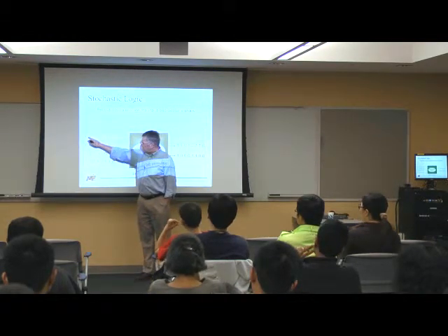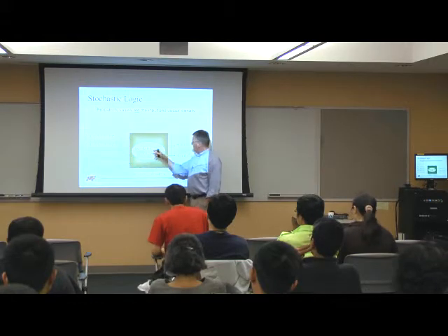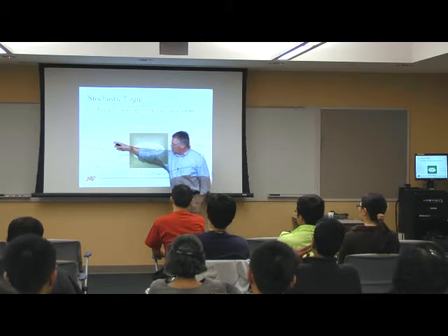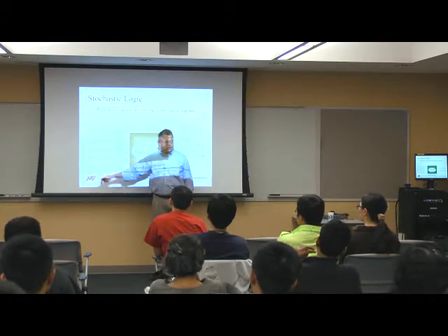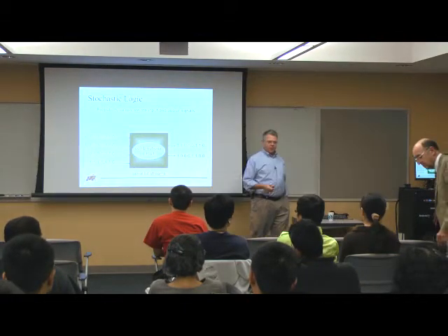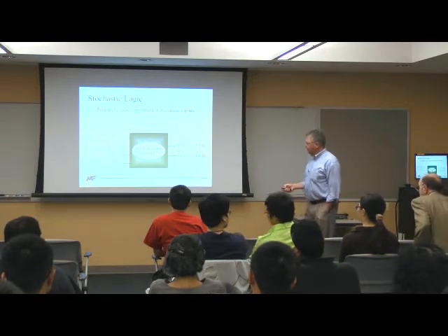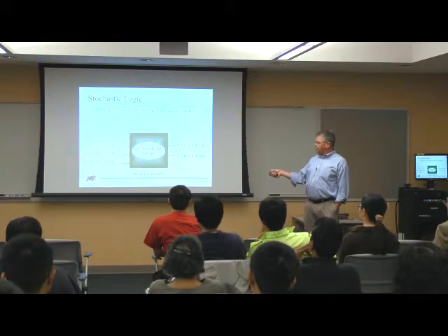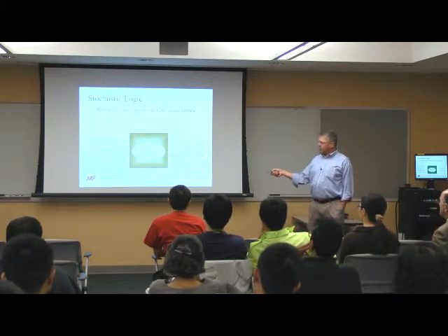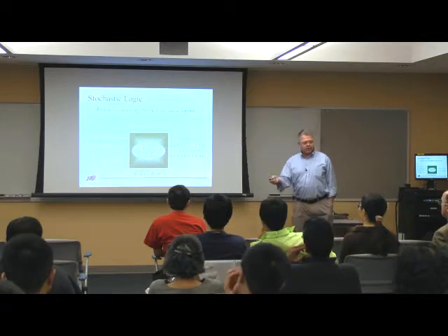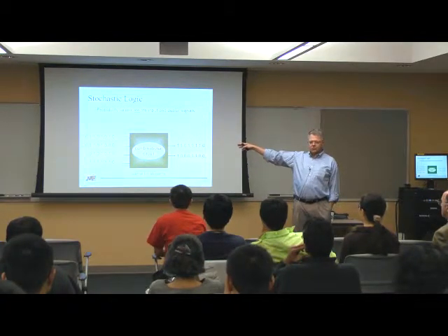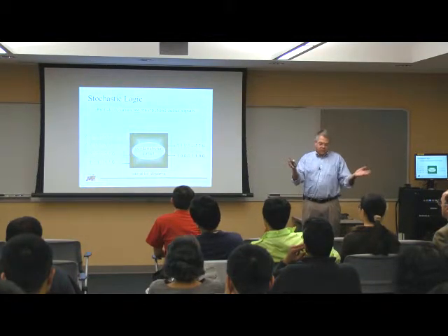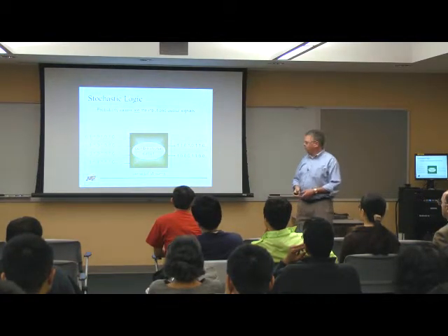On the first clock, my input is 0, 0, 1, 1. My output is 1, 1 here. Then I increment the clock, and my input is now 1, 1, 0, 1, and so forth. So I'm encoding these values, 4/8, for instance, using this bit stream so that over some arbitrary period of time, on average, 4 out of 8 of those bits, or 50% of those bits, are a 1. I don't care what order they're in. I just say over this period of time, half of them are going to be a 1.